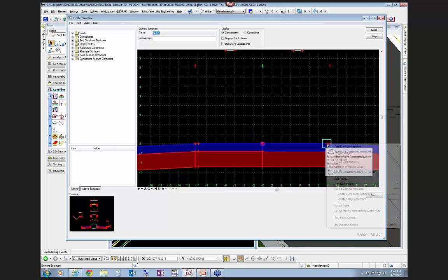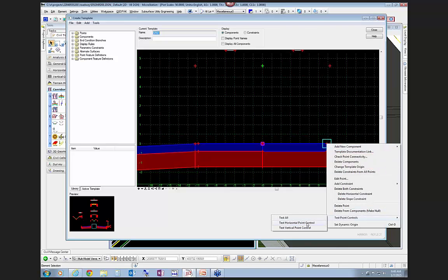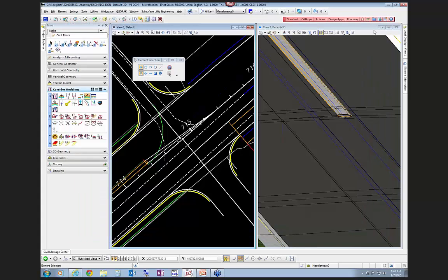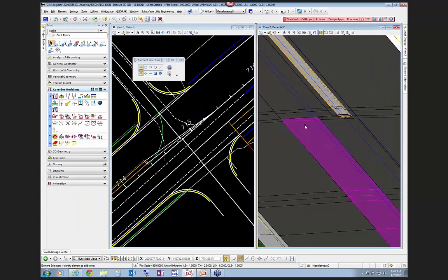And now the way it works is, if you test this horizontal line, you'll see that as this left turn lane tapers out, it's going to move itself back to a normal crown situation. And then when it's up here in the traffic separator, it's basically going to meet the pavement of where the traffic separator is. So the only other thing we need to do then is notice that it's sitting here crowned and it's using that template. So we just need to add these as reference lines or pavement slope references for that particular template. So I'm going to locate the corridor here.